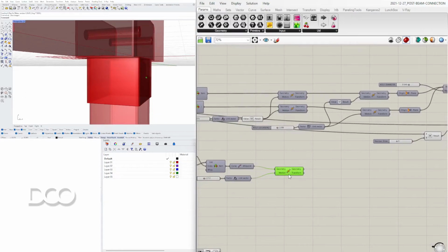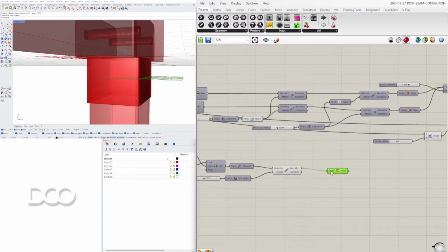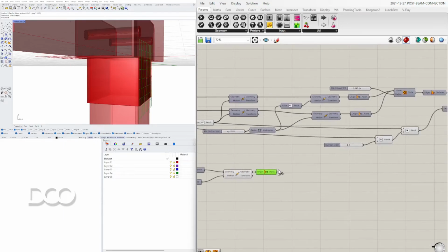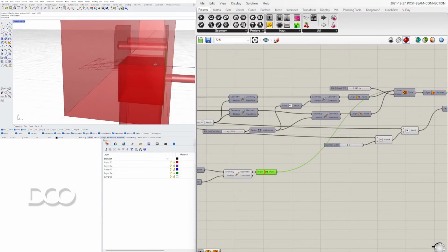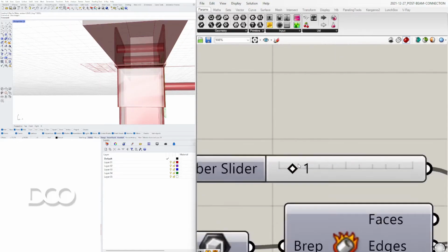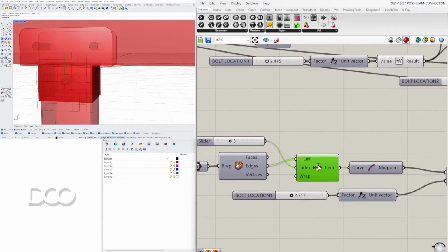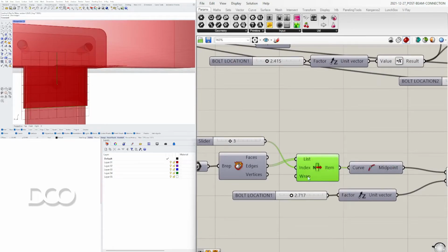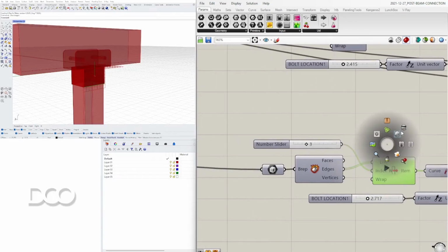Actually, it has to be created using XY plane or YZ plane. And that is what was plugged into the circle. So now, as you can see, I actually picked the edge on this side, so it's extruding it all the way through to the other side. Watch, I can just make sure that I pick the correct edge here. This is the bottom edge of the other side. So I just cycled through, and number 3 was the correct one.